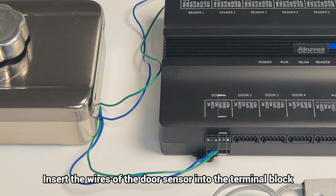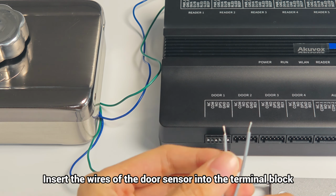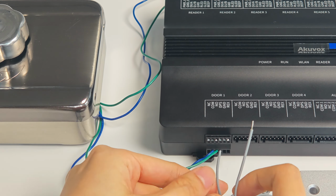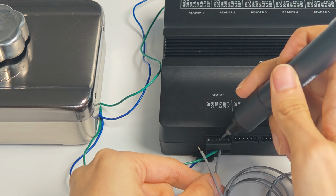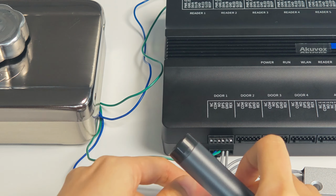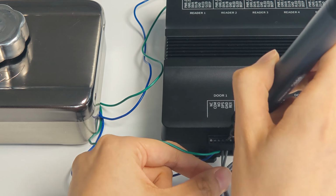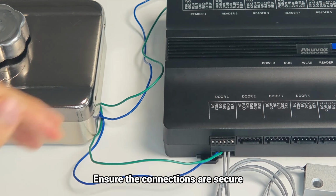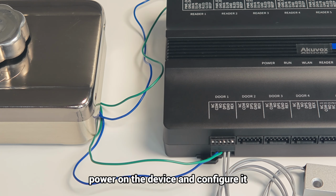Insert the wires of the door sensor into the terminal block. Ensure the connections are secure. Then, power on the device and configure it.